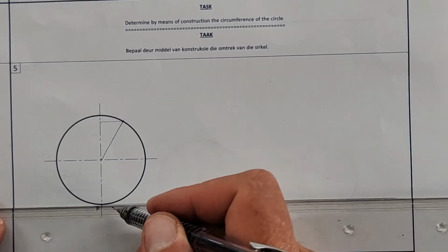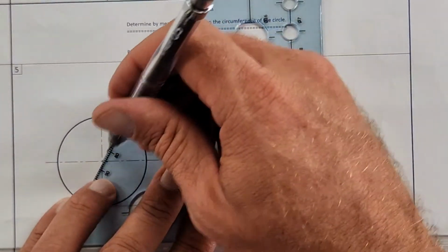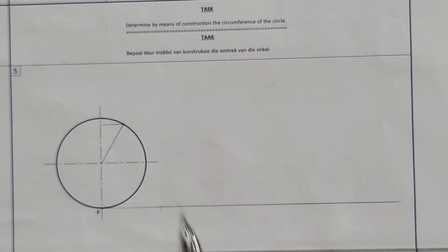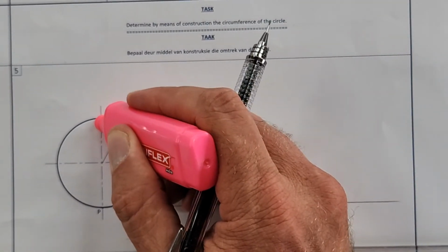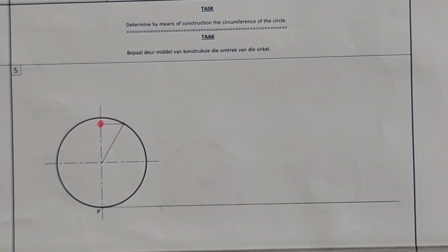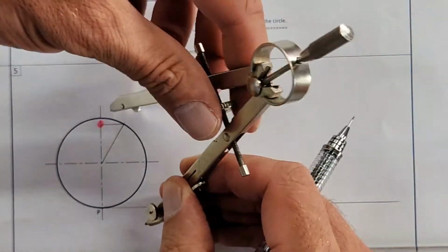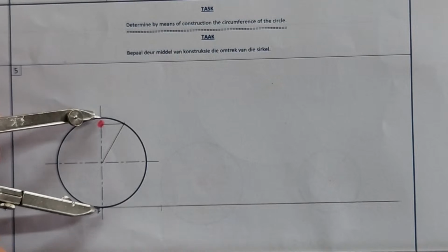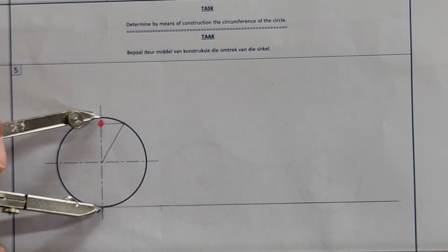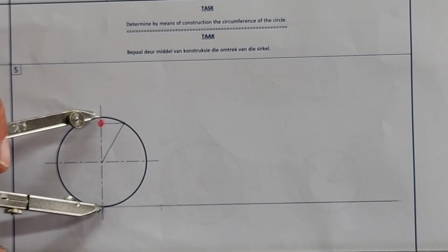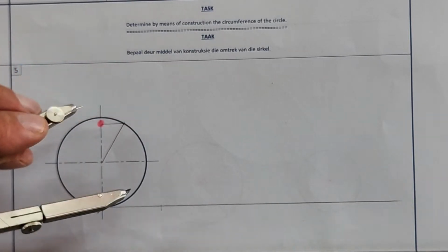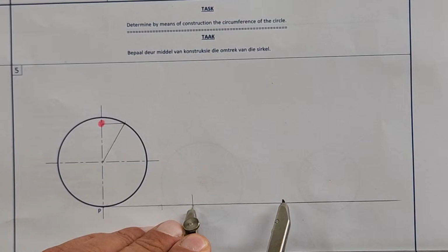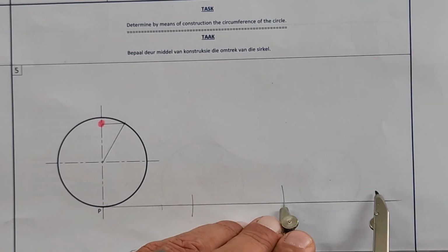We did the first line, construction line, then at 60 degrees to the end, and the line back to that. So we've done all of that to determine this point. That's the important one that we determine now. Okay? Then you take your compass on the diameter. Okay, set it on the diameter. And with confidence, you're starting at P. You go 1, 2, 3.